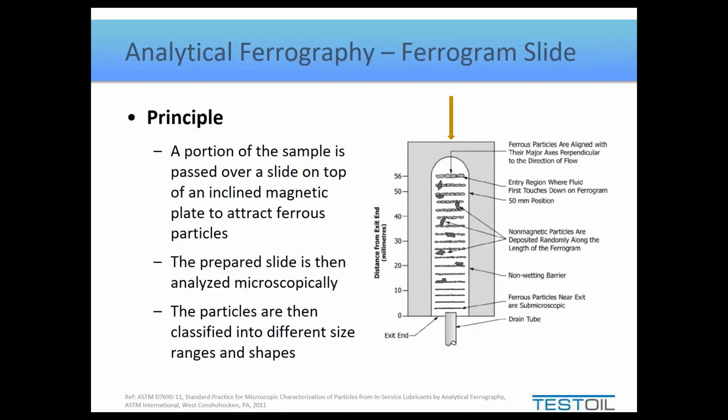Now I know at first glance you're going to say to me that, well, particles would never orient themselves as well as are shown in that picture. And that's because, no, normally under fluid dynamics, particles will settle out largest to smallest. However, they don't align themselves unless we use magnets. And there are a series of magnets placed underneath the slide to encourage this sorting and orientation. So all the ferromagnetic particles will sort out in nice straight lines, as you see there, and all the non-magnetic particles will randomly distribute across the slide.